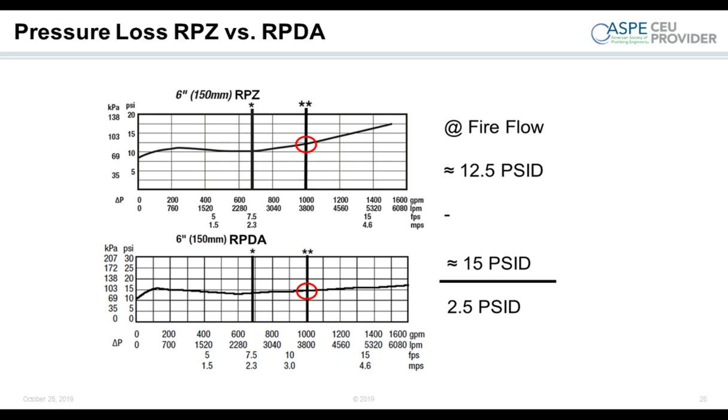You won't find these leaving the factory at exactly 1 PSI per check because after a while, what will happen is hysteresis, right? Those springs get a little bit weaker. As they get worked, all of a sudden your valve starts failing its test. We don't want that, which is why you see it go out a little bit higher.